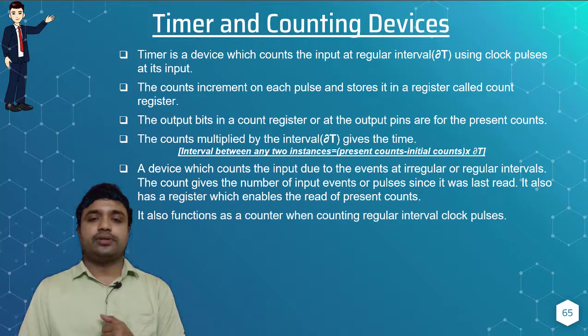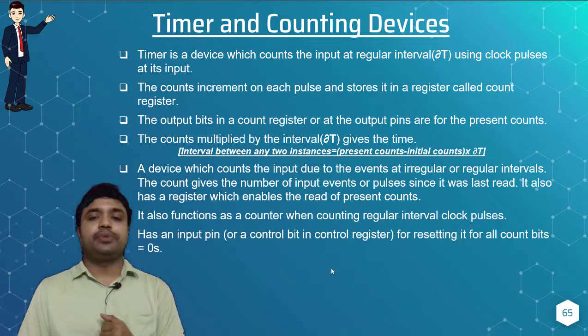It also functions as a counter when counting regular interval clock pulses. So the timer operation can be realized as a counter operation when counting regular interval clock pulses. It has an input pin for resetting, so that all count bits are set to zeros. The register value is reset from the input pin, where the input condition is set for all zeros.